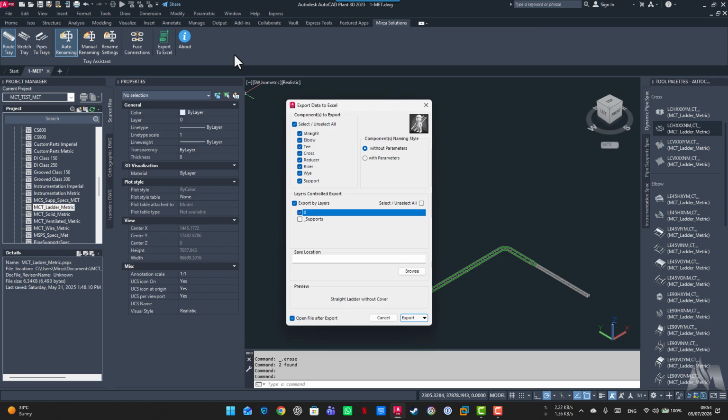So if your component or your layer is locked, frozen, or hidden, then these commands and this export feature will skip them, because that is why we have hidden them and frozen them: we don't want them to be part of our calculation. So these commands will assume that you do not want these changes or this export applied to them. Okay, so let's export, for example, everything.